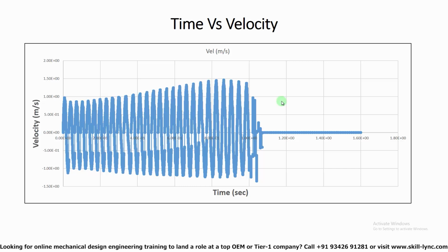Now in addition to this, you will also be looking at pressure load on the spindle, right? So you can just create an animation where you can color the spindle by pressure using Insight or ParaView, and you can take that pressure map and feed that into an FEA solver for basic strength calculations.